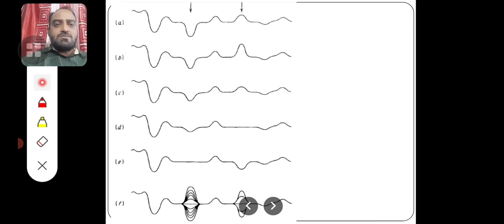So what we can do is sum it up to understand where a moving target is. When you sum up all these scans, the resultant will be like this, as shown in this figure. Wherever there are multiple changes, it looks like a butterfly, so we call it a butterfly diagram. Using this butterfly diagram, wherever there is a butterfly, you can estimate there is a moving target. Understood?